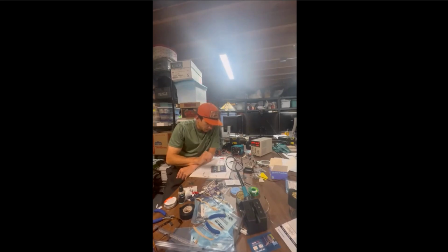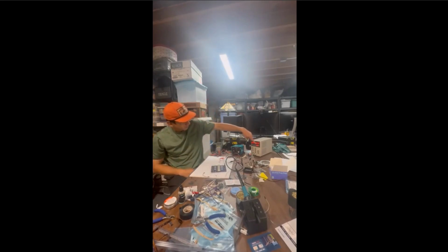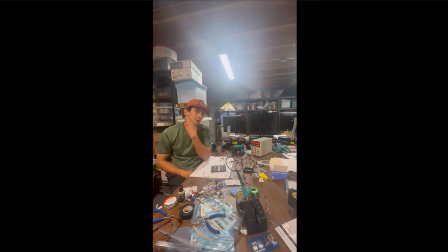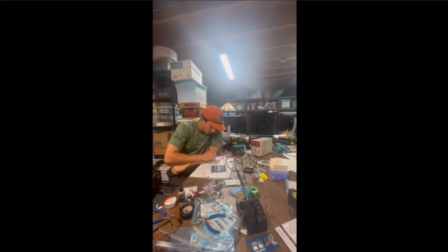So now I have the current limited at 250 milliamps. I'm suspecting it'll need a little more power, and my voltage is set to 5 volts. And so this final test is going, well, I should stop saying final. This next test is seeing if the board will turn on and operate correctly. I've tested 0 short circuits are happening, every power and ground, used a multimeter, did the continuity test. It's looking good. So here we go.